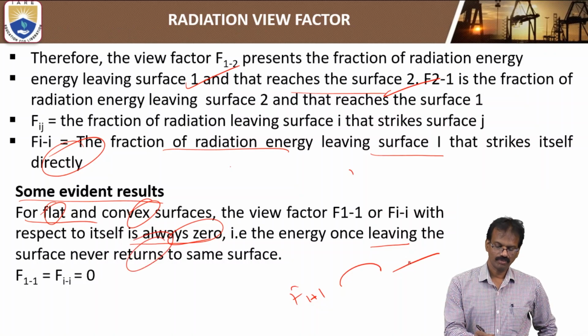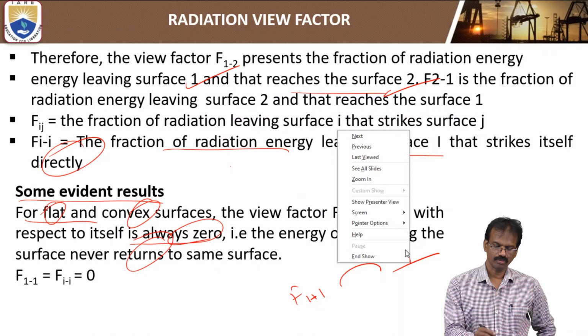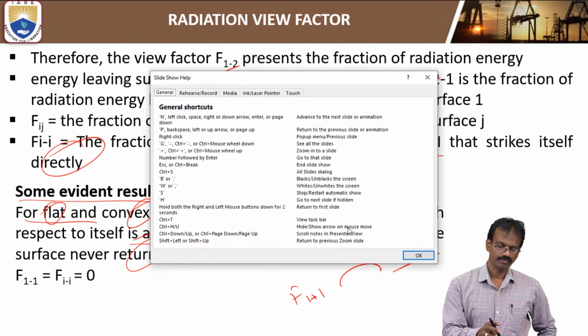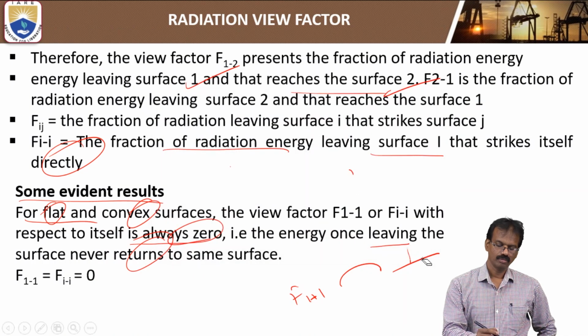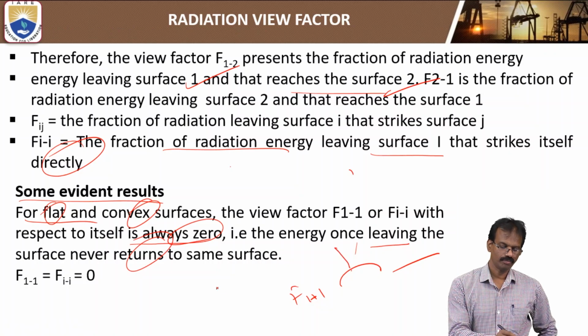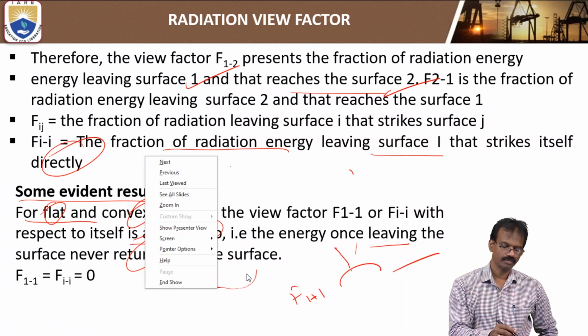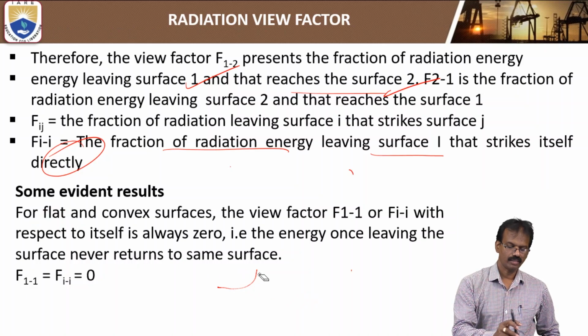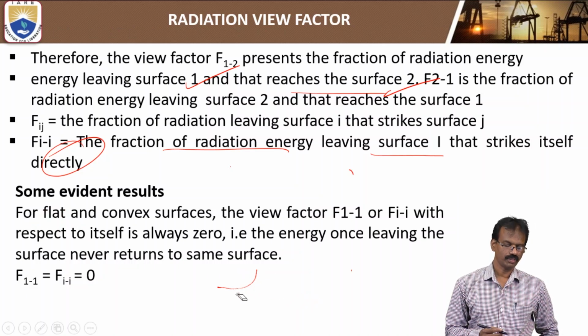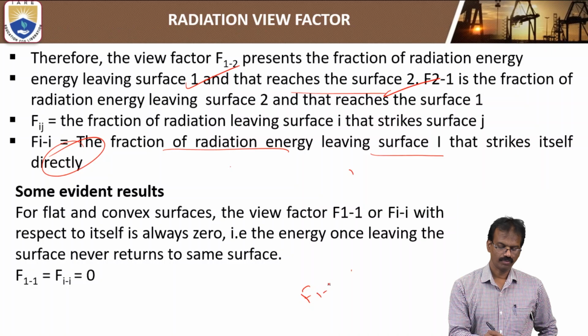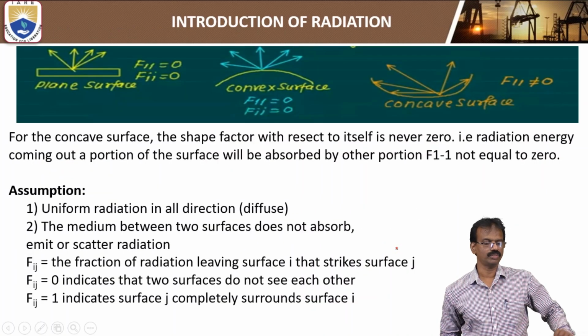If energy leaves from here, it never touches the same surface again. So for flat and convex surfaces, you can take F11 equal to Fii equal to 0.